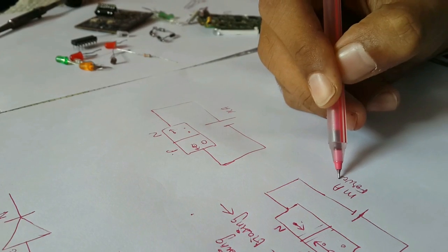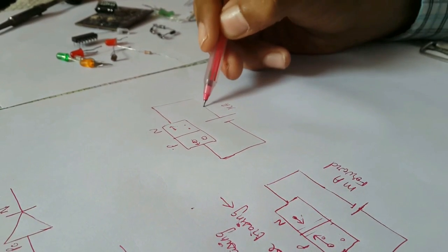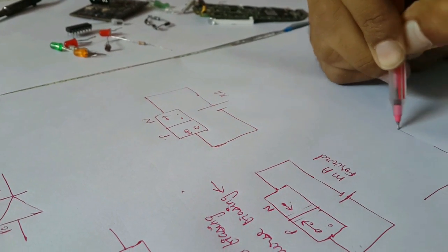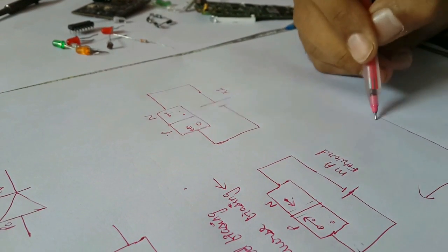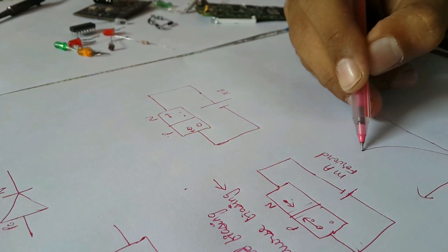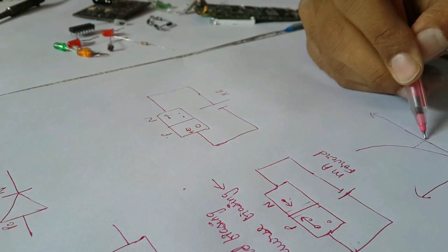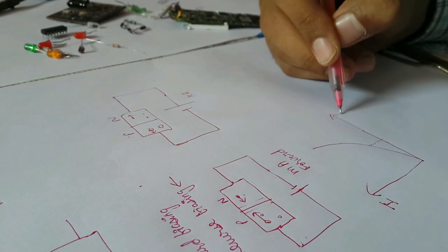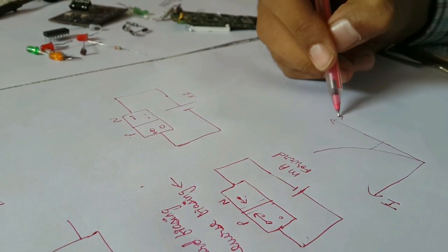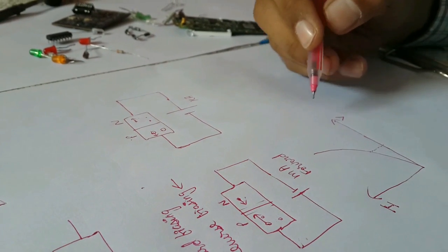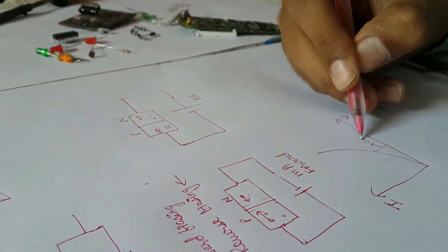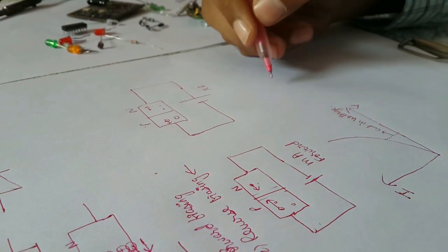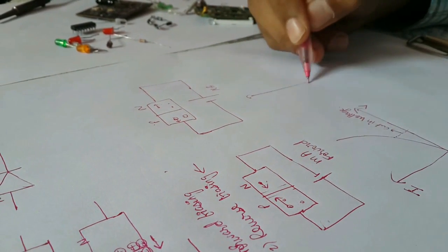So for a good amount of current we use forward bias, and for some other purpose we use reverse bias. The forward characteristics we get for a diode are like that. This is the IV characteristics, the V versus I curve of the semiconductor device, known as the characteristics curve. Here this is known as the cut-in voltage, after which the voltage and current rapidly increase, and for the reverse bias